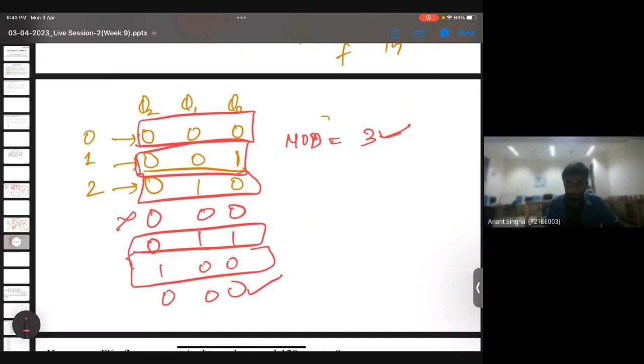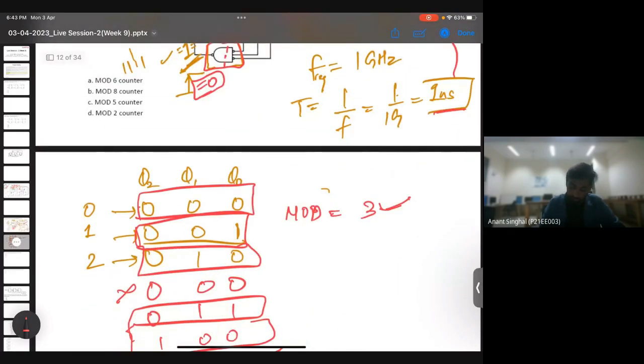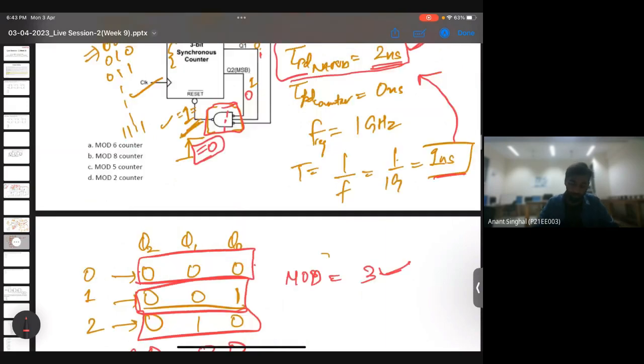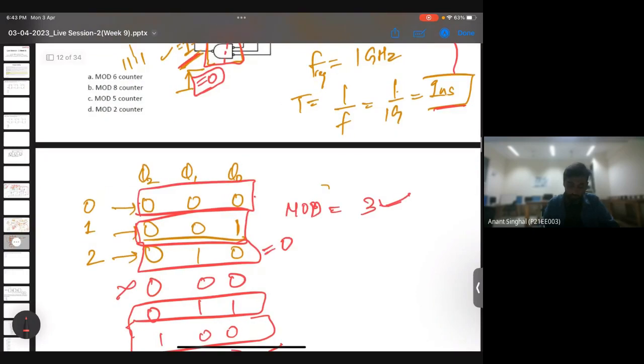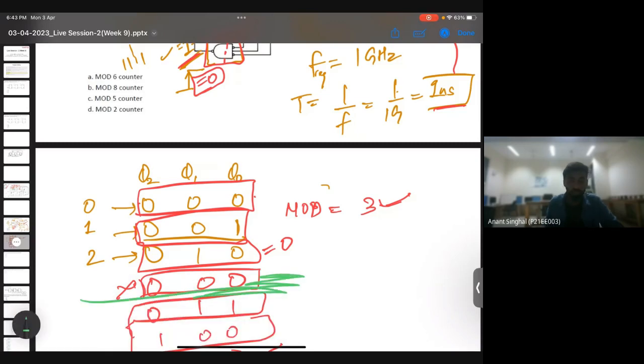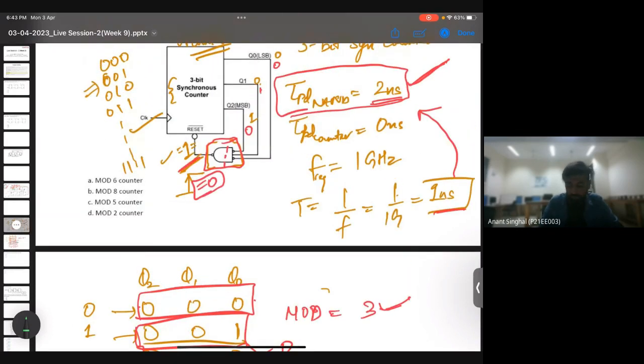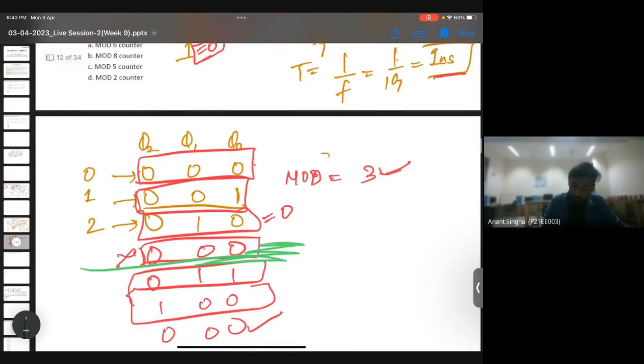No, sir. Okay, fine. I'll try to explain again. What was happening is we were checking, when it is 1, we are giving the next clock. So once it got 0, we concluded that the next stage will be 0 0 0, right? Till here it is clear? Yes, sir. Okay, now I'll repeat. The question says that the propagation delay of the NAND gate is 2 nanoseconds. So to make this 0 0 0, it will take 2 nanoseconds for the NAND gate, right?